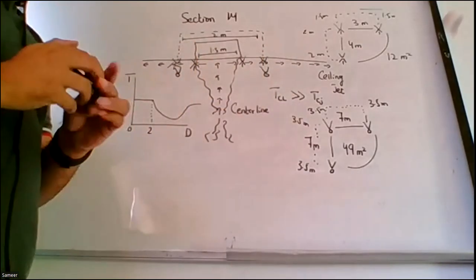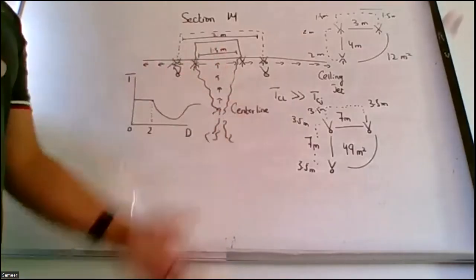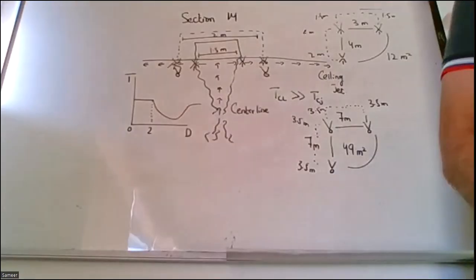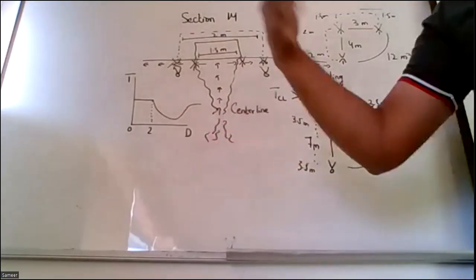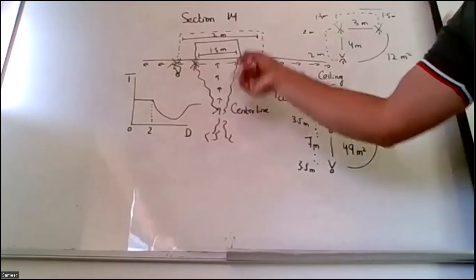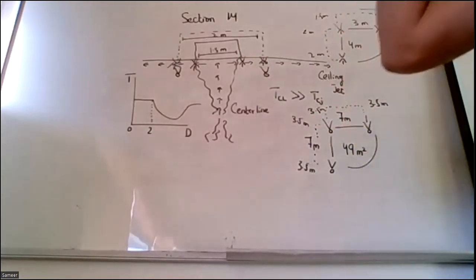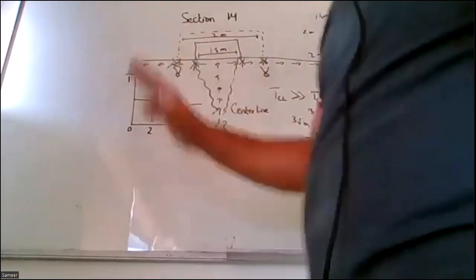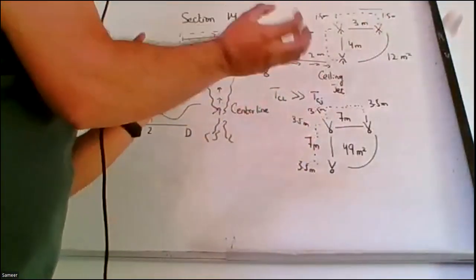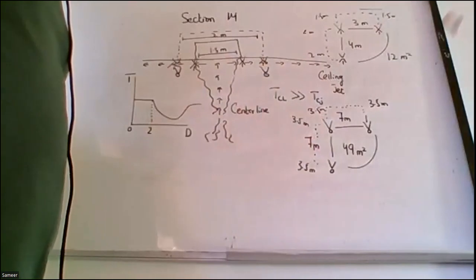Okay, so basically that all depends upon the center line width, the center line effectiveness. So I cannot predict where the center line will be. It could be anywhere, but within that distance, my convective device should be there, either a heat detector or a sprinkler. Based on the requirements, it should be there. That's why I have specific distances for the convective devices.